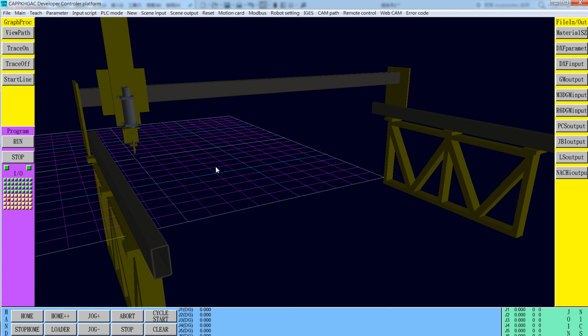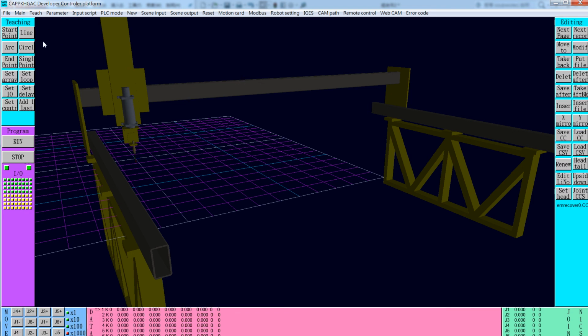And then we have to check the parent and the children's relationship by means of the teach menu. The first one is for X movements. Press the button here. Each press increases by 10. Right now 110, and the dynamic joint will reflect the correct position just in here.